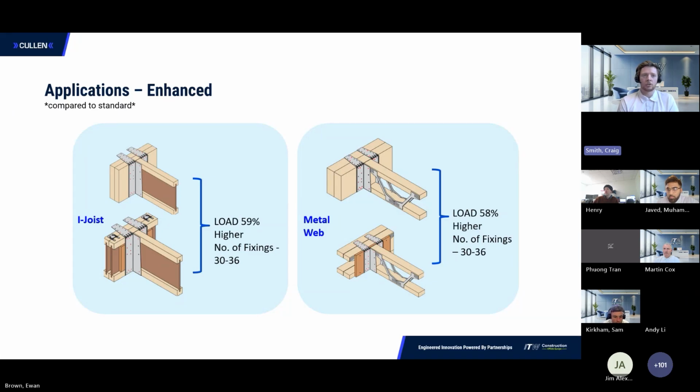And then again, just a nod to, it's probably useful to be using a PPN at this point if you're installing onto metal web, as the nail will need to potentially pierce the metal web in order to get good embedment into the gusset. The load capacity increases from less than 20 kilonewtons to around 30 kilonewtons by doing this application, and also similar sort of nailing for those top tabs. The header nailing rule is minimum of 4 nails into the rear header and 2 into the front header. So keeping the same rule.